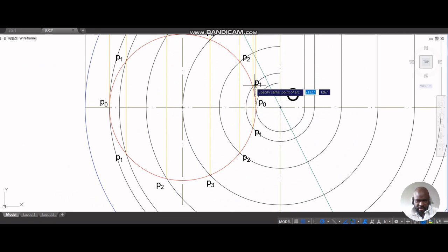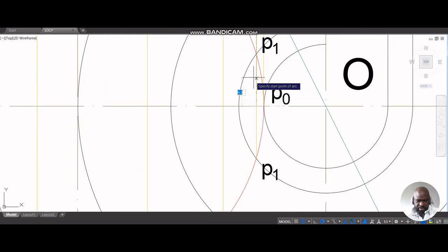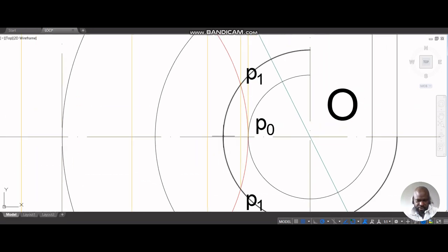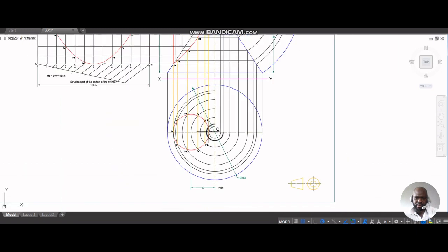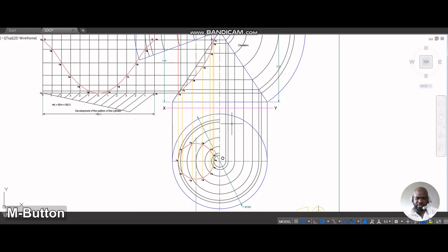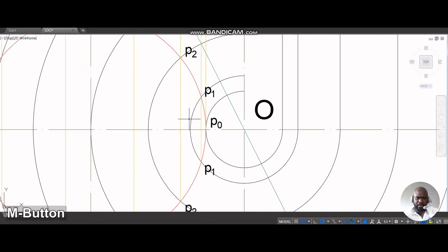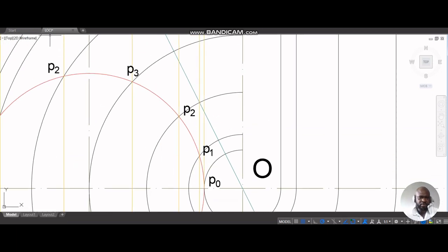So the next point is P1. With a line joining P1 up there, I use 8.4 as my radius. You could choose this point, this curve, with reference 0 to this point. In actual fact, that is what it should be, because that's the cutting plane, and these radial lines are actually the cutting planes that we have extended. So that's what it should be. So let's hit this point. It's 8.9. That matches the radius.